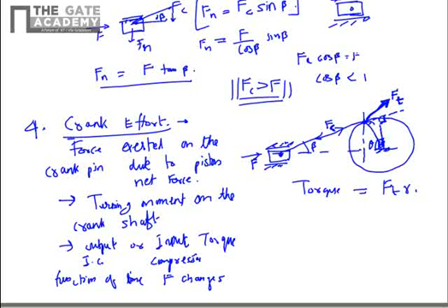In this triangle, the connecting rod is extrapolated to a point, say D. This is A, this is B, this is O. So AD is extrapolated, and the angle OAD is known. You know that the exterior angle is the sum of the opposite interior angles from simple trigonometry. So this becomes beta plus theta.